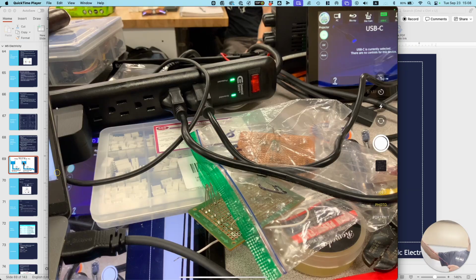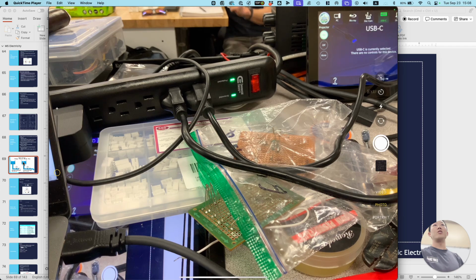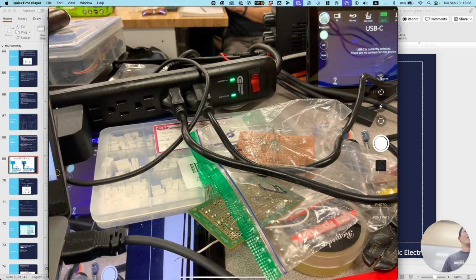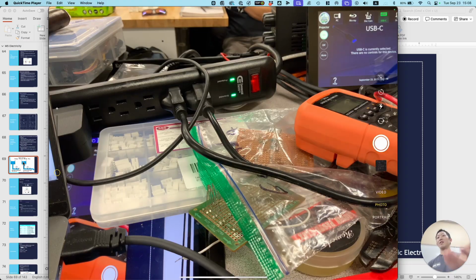So yeah, if you have a multimeter, you can actually check your individual batteries. They all tell you what the rating should be, right? If you look at the battery, it should say 9 volts on there. So this is how you can check. Let's say you have a bunch of batteries and you don't know if they're good or not. Instead of having to plug into some device, you could just measure it on a multimeter.